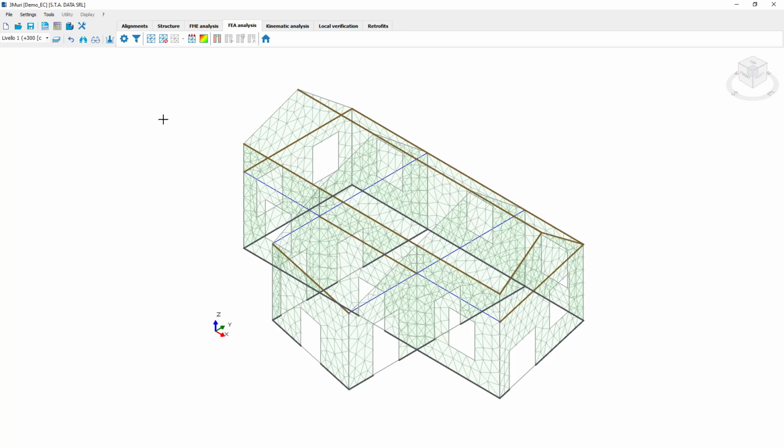On the other hand, the FEM approach is going to be very useful in the case of highly irregular distributions of openings along walls and height, significant presence of walls that don't have any openings, and for example, when I wish to examine more precisely the distribution of floor loads in the masonry, but this means accepting longer calculation times. And of course, I am willing to go into detailed verifications of various masonry piers in order to optimize the verification as closely as possible to reality.